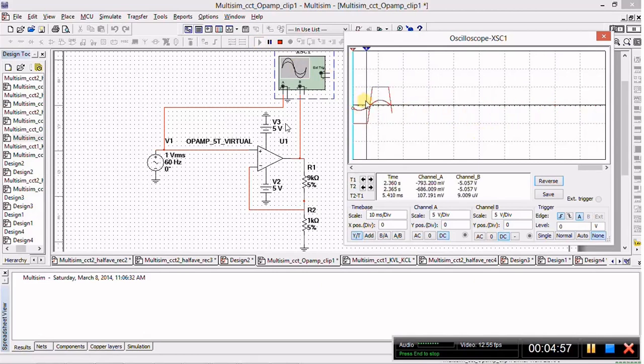The trace at the bottom, the smaller sinusoidally varying one, is the input trace. The taller one that is flattened at the top and bottom is the output waveform, and it is experiencing a phenomenon called clipping. Clipping occurs when you try to amplify the output to a greater value than the source.